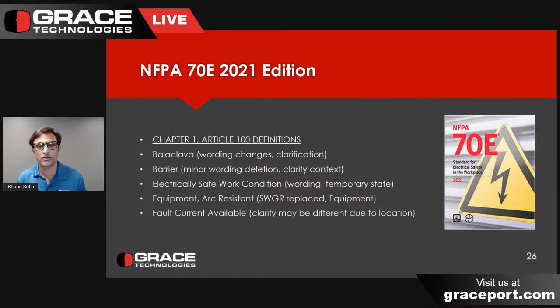It is the state wherein all the hazardous conductors or circuit parts to which a worker might be exposed are maintained in a de-energized state for the purpose of temporarily eliminating the hazard. That's the language, right? If you look at that new wording, there's an informational note that's been added to give you additional clarity on what exactly the paragraph itself means within the electrically safe work condition.